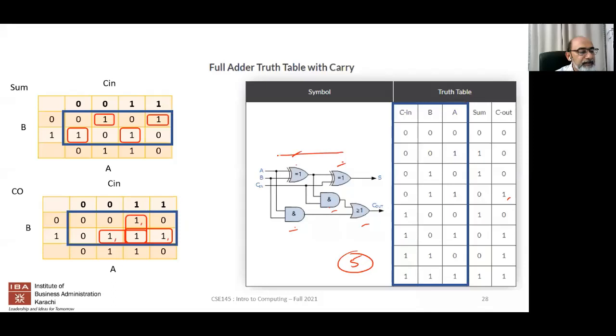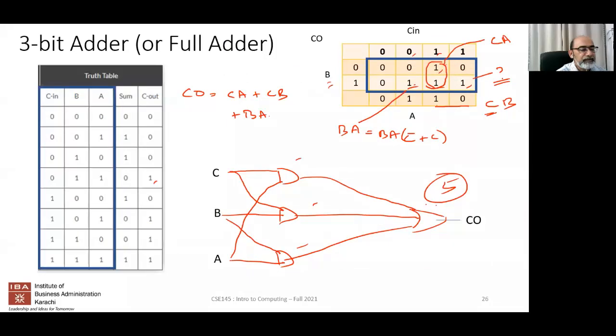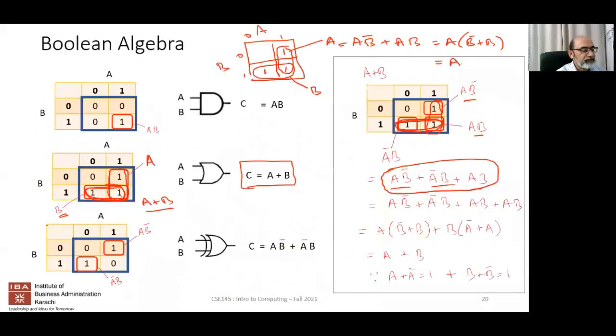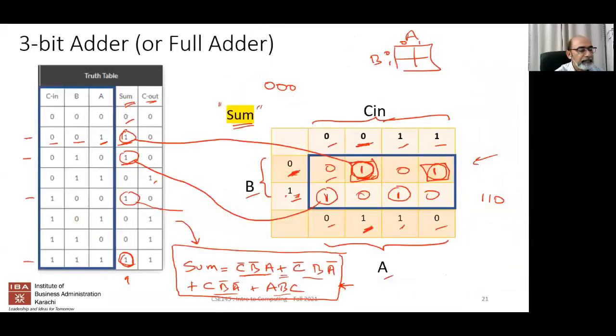S basically is saying that two XOR gates are combined together. Now, this is a little tricky, but if you get some experience, you can see that the XOR gate, originally corresponding to this combination, had a 1 in opposite quadrants, sort of like this. So this visual look can tell you that this corresponds to an XOR of A and B, however you pronounce it.